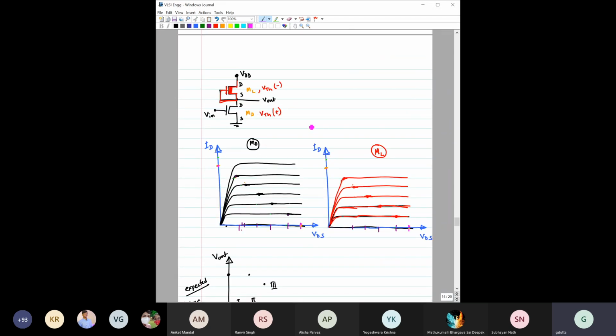So then consider this circuit, as shown here, right? What we have done: the bottom part, that is this part, is the normal NMOS, on top of which the load, which was earlier a resistive load, we have replaced by this. So this is what? This is a depletion mode MOSFET, right? And how have we connected this? We have to be careful. See, this is the gate terminal. Now the gate terminal has been connected with the source terminal, shorted.